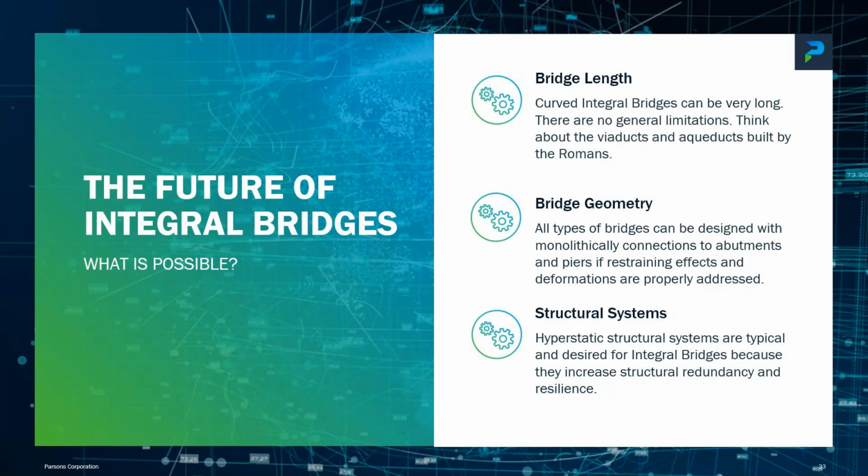From a structural systems perspective, you now deal with hyperstatic structural systems, and they are obviously a little bit more complicated because stiffness matters when compared to statically determined systems. You shouldn't see that as a disadvantage, you should see it as an advantage, because hyperstatic structural systems can activate secondary load paths because you have that structural redundancy. But you need to aim for it, and you need to design for that performance. And that's where performance-based design comes into play.